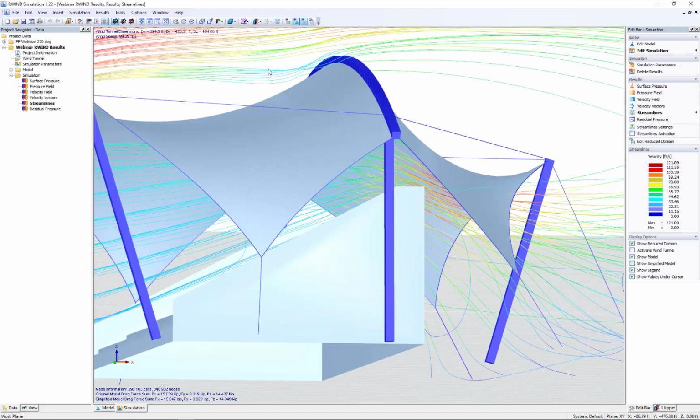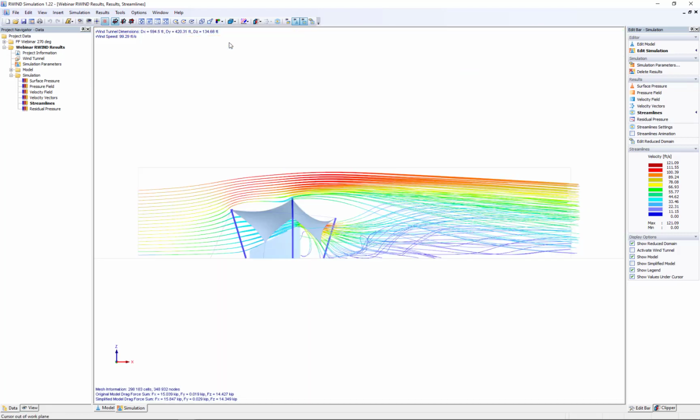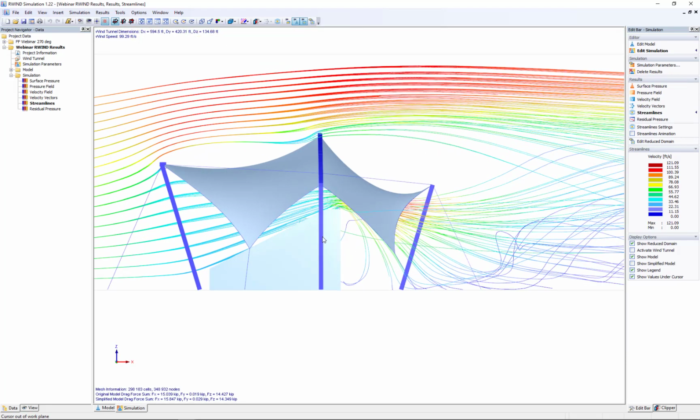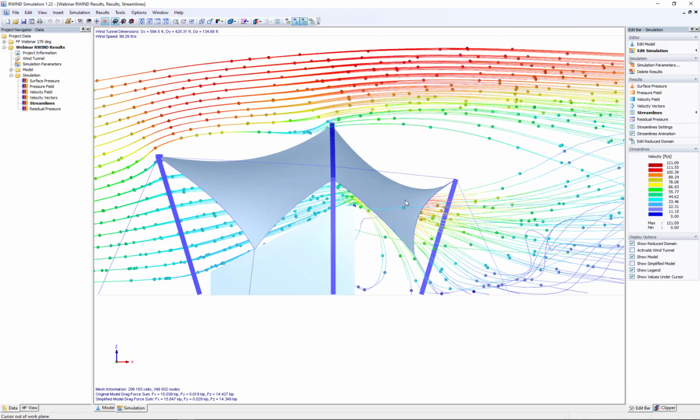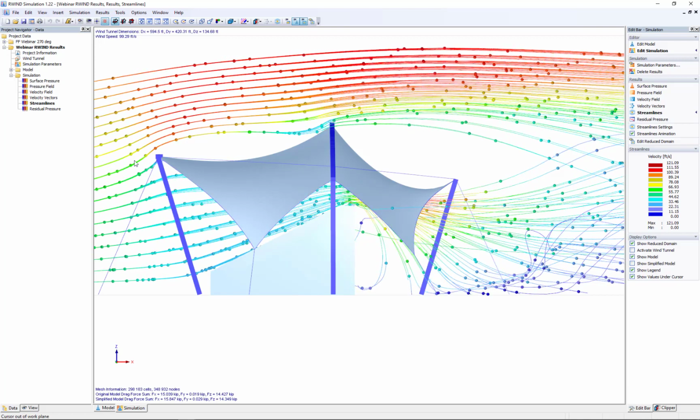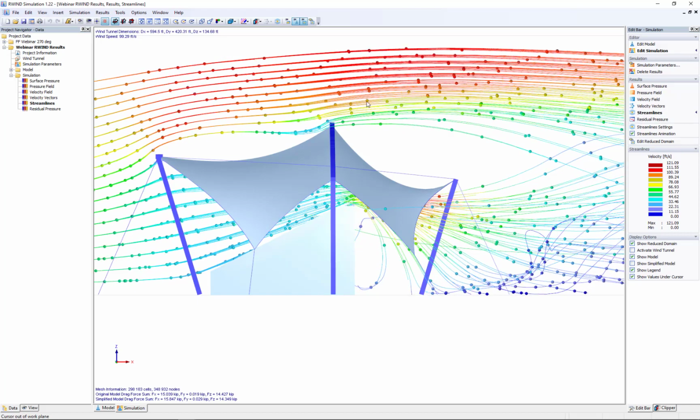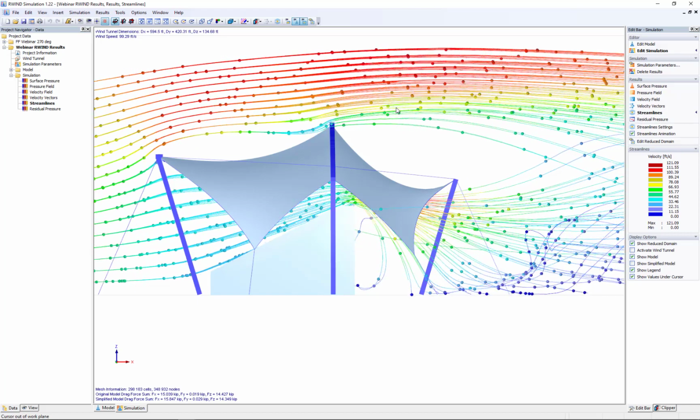And we can turn this back into the Y direction. What also is powerful is let's turn on our streamline animation. So for this, I've set this to particles to follow those streamlines, and you can see them hitting the stair structure and then passing out through the top. Now, additionally, we have the wind, of course, just passing through the top here as well.